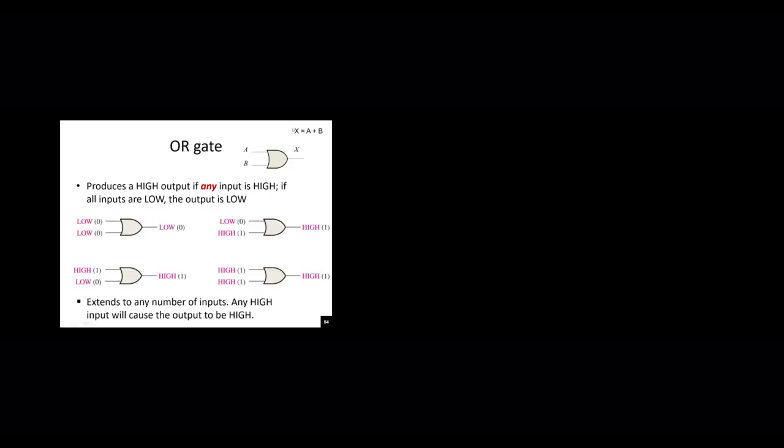When we want to draw an OR gate in a circuit diagram, we curve the input and it comes to a sort of a point at the output. That's an OR gate. And an XOR gate is just an OR gate with a double line here on the input. So you'll just get used to those different representations of those logic gates when you're drawing up your circuits.